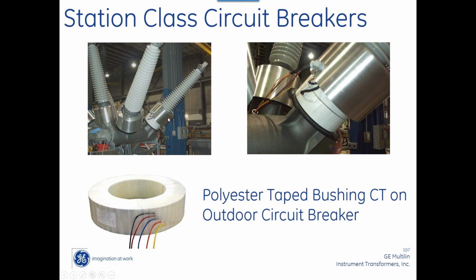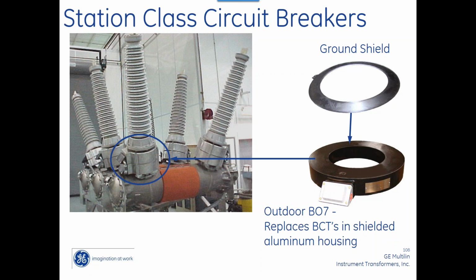They're actually using 600 volt CTs, and this is on a 69 or 72 or 128 or 250 kV system. But they've got huge insulation levels because of the insulators. So here's an application where I could have a 600 volt CT on a 240 or 250 kV system. In switchgear, I typically don't see it over 35 kV.